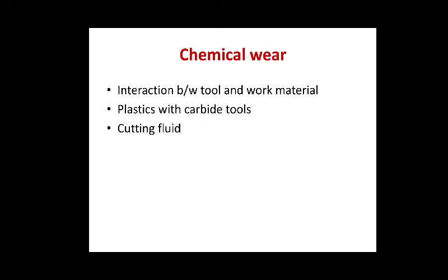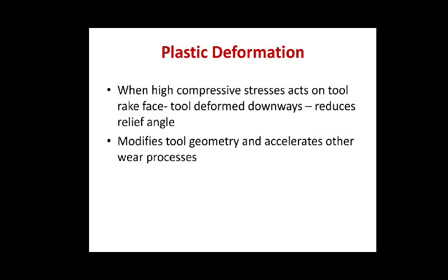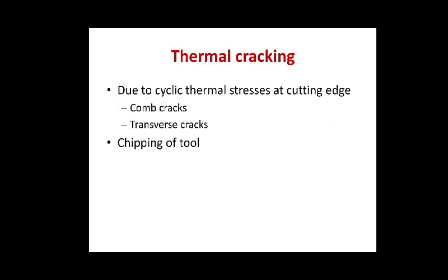Plastic deformation: when high compressive stresses act on the tool face, the tool is deformed downwards, reducing the relief angle, modifying tool geometry and accelerating other wear processes.